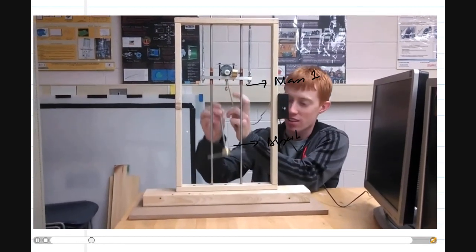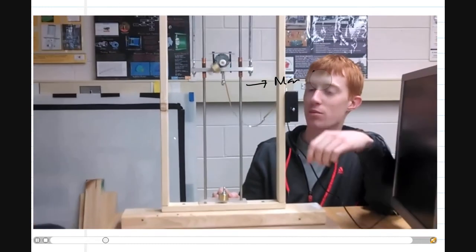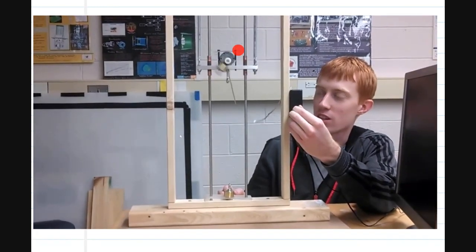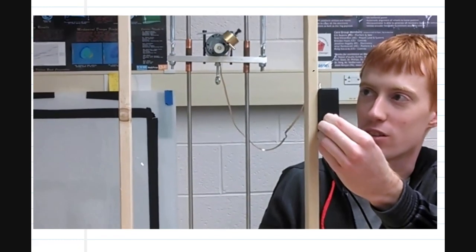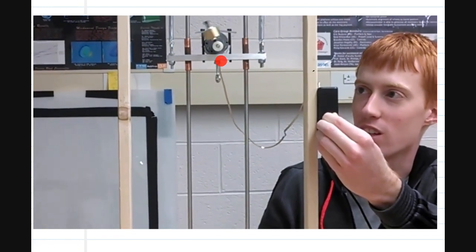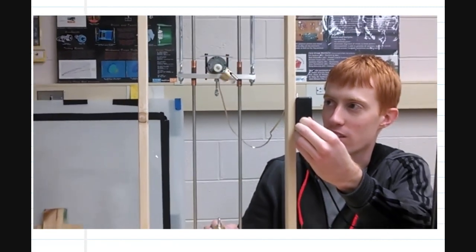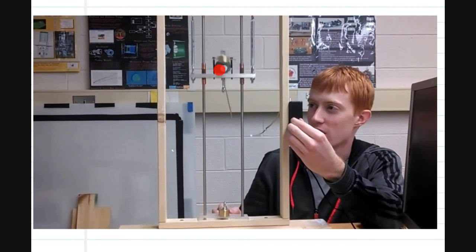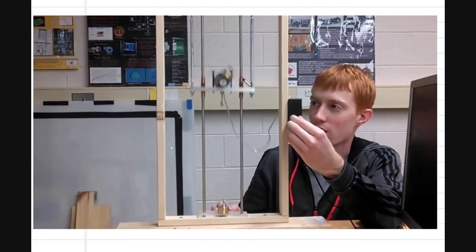Clear? Now what he is doing is this: we have an unbalanced mass on this main mass and spring. He is finding the natural frequency such that if the excitation frequency, which is the rotational frequency of this unbalanced mass, becomes equal to the natural frequency of K1 and M1, it tends to resonate.